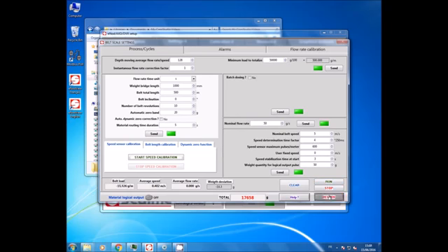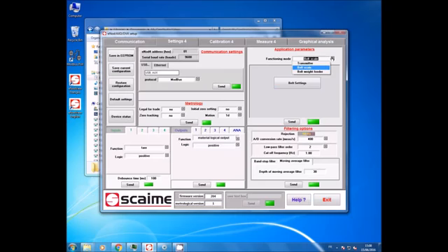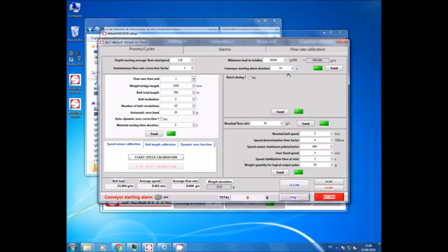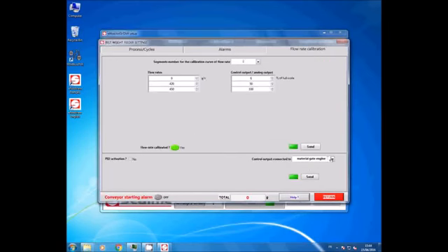Switch to belt feeder. Set your analog output to flow rate control and save to EEPROM. Back in Parameters. Finally, assign the analog output to the material or the belt drive, as in my example.